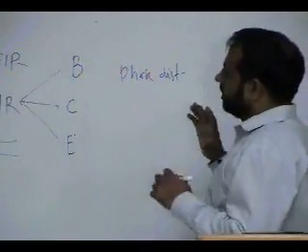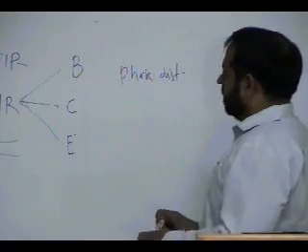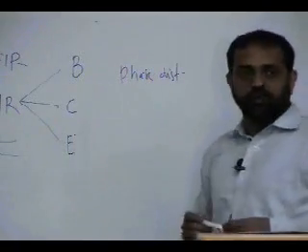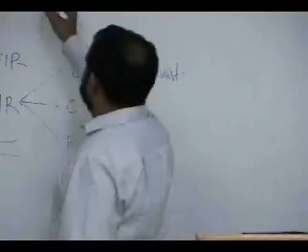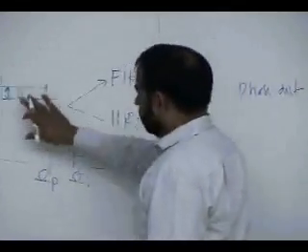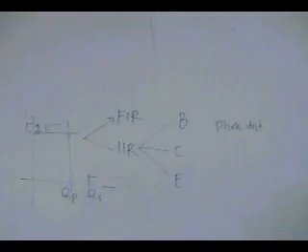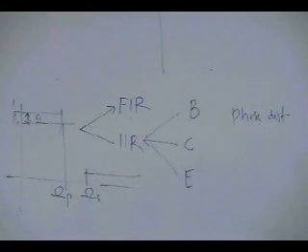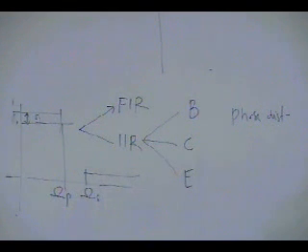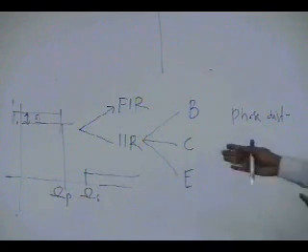What we learned in the first part of the course is analysis. In analysis, we said the Fourier frequency response is good because it tells you how the frequencies of the input signal will be shaped. And then we said the Z transform is good because it tells you something about stability. All you have to know is that all the poles are inside the unit circle. And how do you know that? We'll find out.